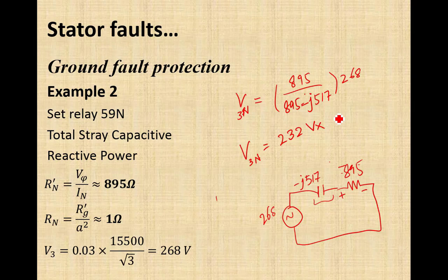Okay, when this voltage is referred to the secondary side of that grounding transformer, multiplied with the ratio, that is 480 over 14,400 volt, this will result in 7.73 volt.